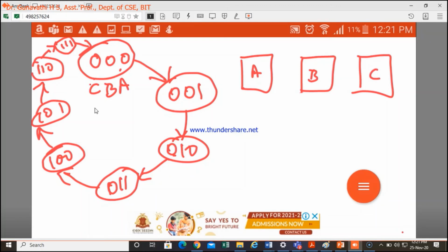So you decide what you use it here. So be careful with the inputs. It's not necessarily this, but you compute the inputs there, based on that you write. Why I'm telling this? Because you just observe what is the most significant bit, what are the inputs you computed for that flip-flop, based on that you write it. Blindly, if you are copying one page, you'll copy the truth table from somebody else, and someone will copy your circuit diagram. If these two are not matching, then the entire thing will go wrong. Be careful what you are going to write there.